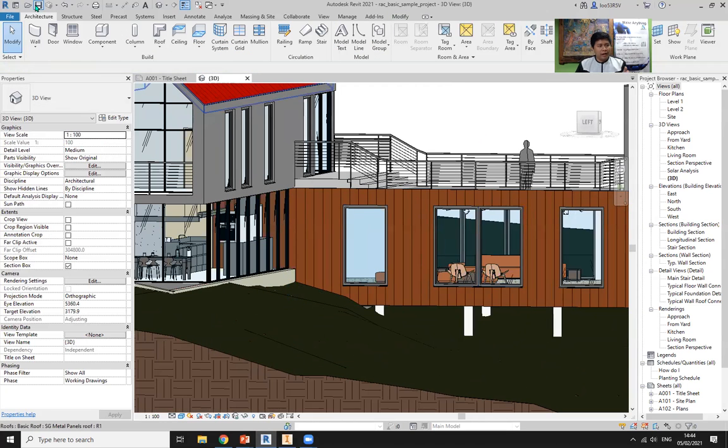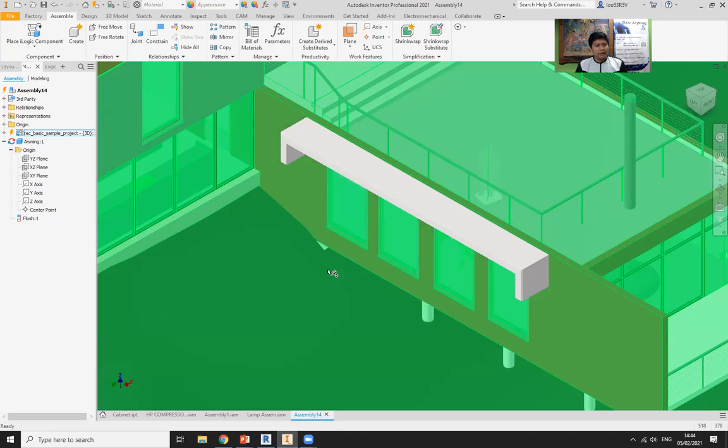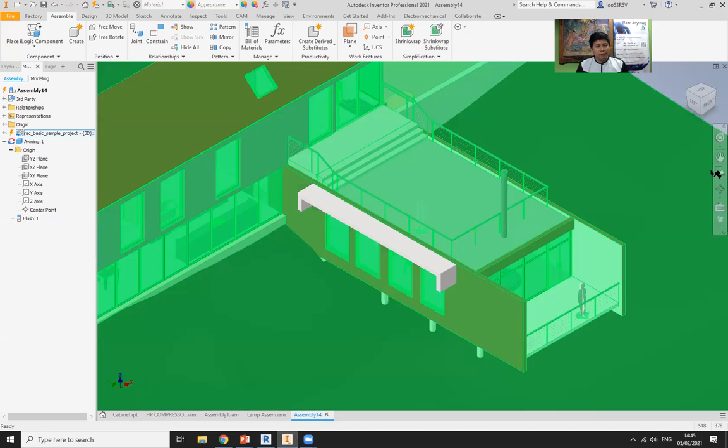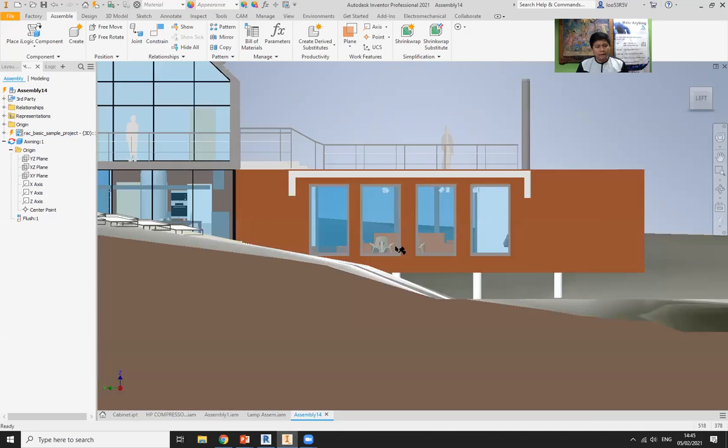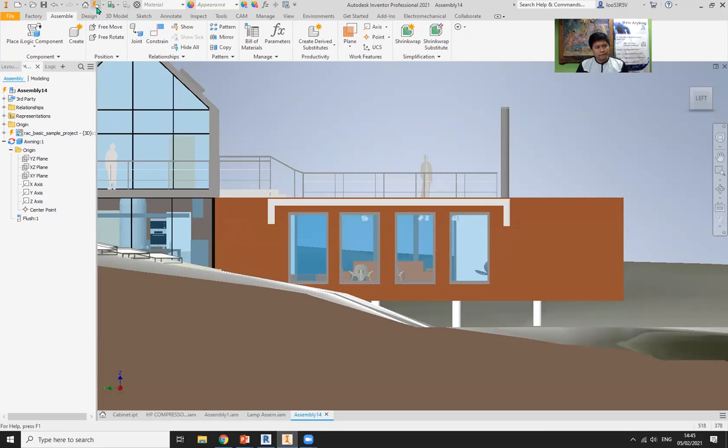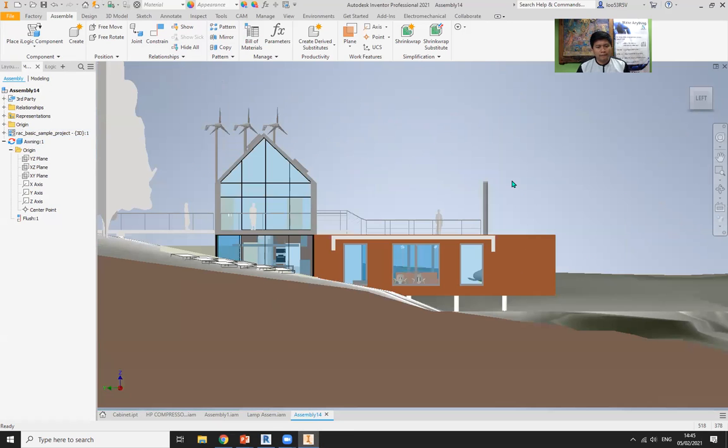Okay, when I save this Revit family and directly open my Inventor, you see that my Inventor will have one option to update on top here. And the symbol also appears here. So what you need to do is just click on this update. So later you see that this modeling will also update, referring to your Revit drawing. Okay, now updated.